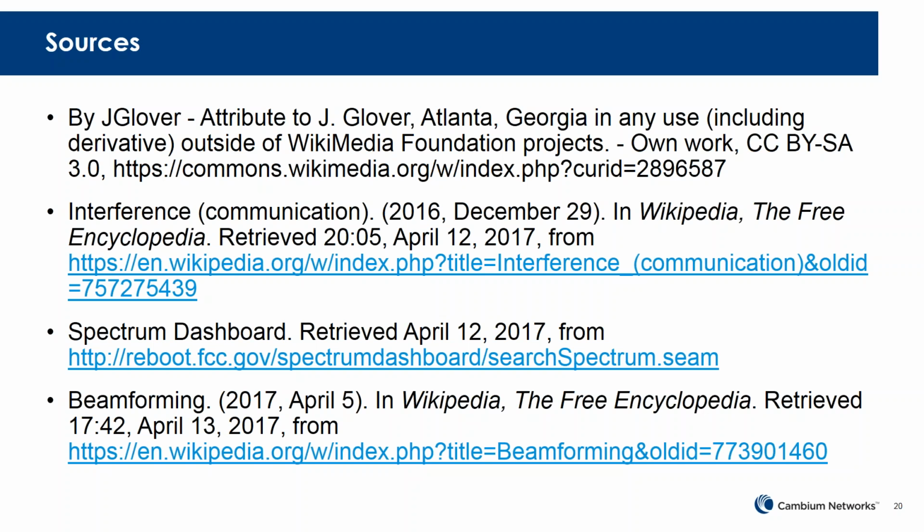So distance absolutely has an effect. If you remember what Dave Hensley talked about last time with free space path loss, distance is greatly going to diminish the receive level at the access point, and then vice versa. As far as adding the antenna gain, for Cambium products, the way that it works is the access point is actively listening to each individual subscriber, and it doesn't know what that antenna gain is as that signal comes in.